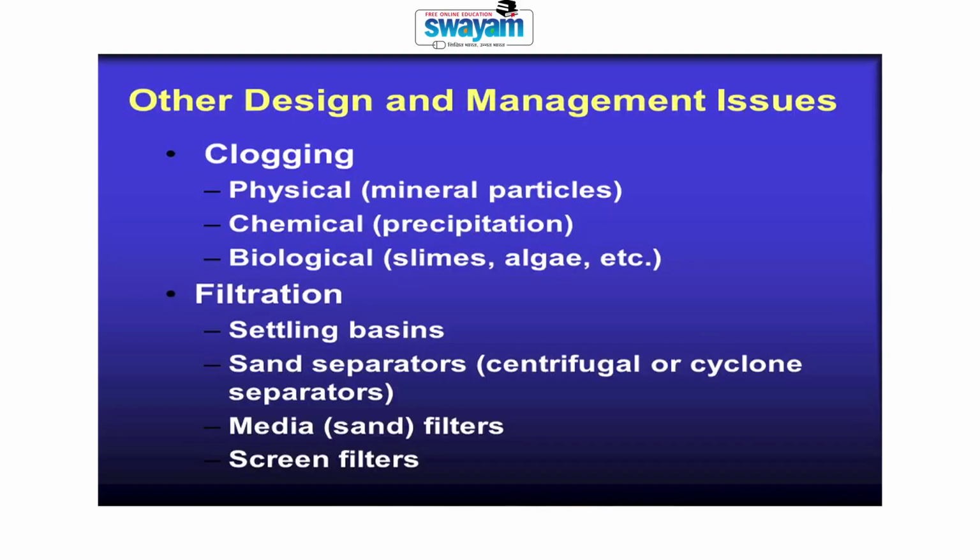Other design and management issues are clogging. As I discussed, you have physical clogging, chemical clogging, and biological clogging. You need to have proper filtration, regularly managing the filtration system through a settling basin, sand separator or sand filters, typical centrifugal or cyclone filters, media filters and screen filters, by which you can clean the water before it is delivered to the plant.